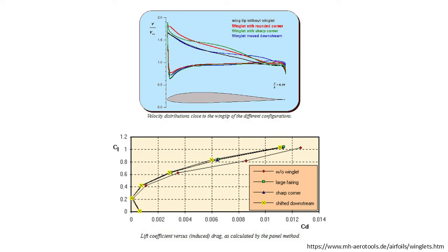So far we discussed the boundary layer effects of the study and the friction drag associated with the winglet addition, but let's not stray from what winglets intend to do, and that is decrease the induced drag. We can discuss the boundary layer effects and the pressure distributions all that we want, but they wouldn't really be useful if the different winglet configurations here showed majorly different induced drag results.